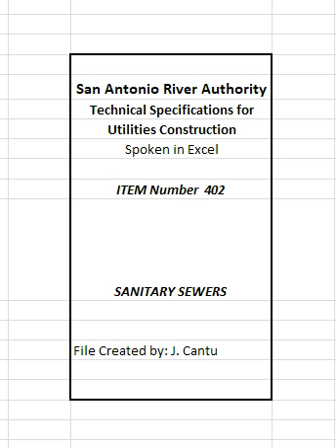Fittings for ductile iron pipe shall have not less than the thickness, class, or pressure rating specified for ductile iron pipe. Fittings shall be furnished with all necessary glands, gaskets, bolts, etc., as may be required to complete the joints. Rubber gasket joints for mechanical joints or push-on type joints shall conform to the requirements of ANSI Standard A21.11/AWWA C111. All ductile iron pipe and fittings shall be polyethylene lined.